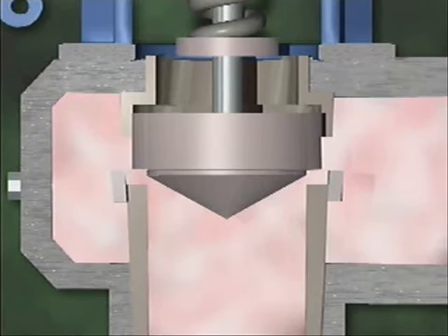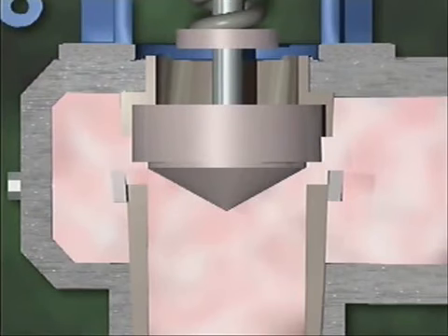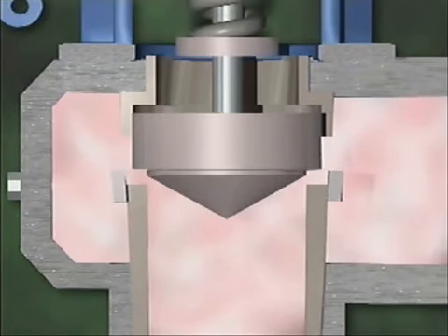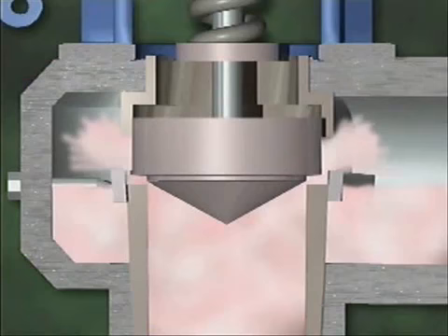If the pressure in the system continues to increase, the velocity of the escaping fluid will also increase, causing the disc to gradually lift higher until it reaches the fully open position. Since the initial opening of the safety valve is about 60%, a large volume of fluid is allowed to escape quickly. After the excess pressure in the system has been relieved, the system pressure will begin to drop. As pressure decreases, the velocity of the escaping fluid also decreases. Spring tension begins to take over, pushing the disc down.